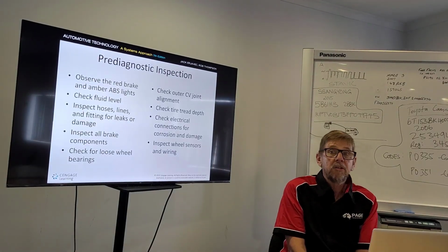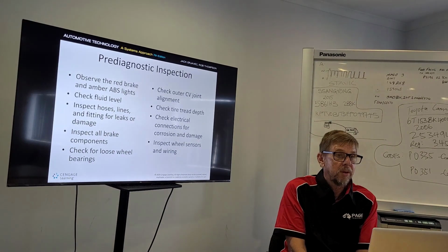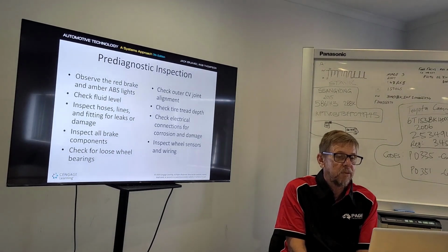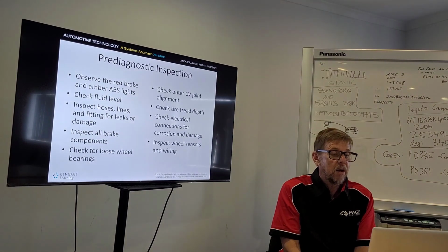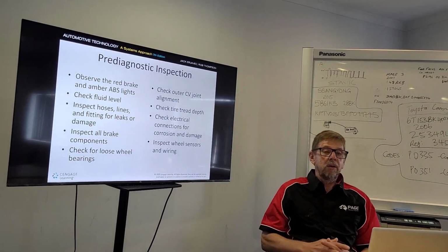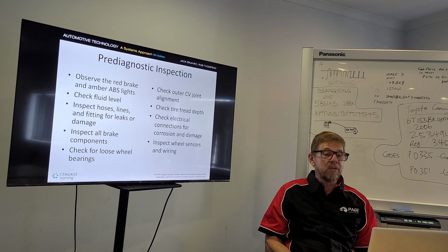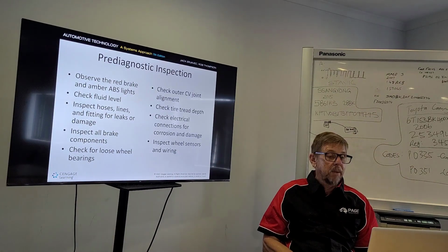So pre-diagnostic inspections are all very important, as I say. We want to always go through the process that we have. We want to observe and verify that the brake light or the ABS light or whatever is the customer's complaint is a real complaint.